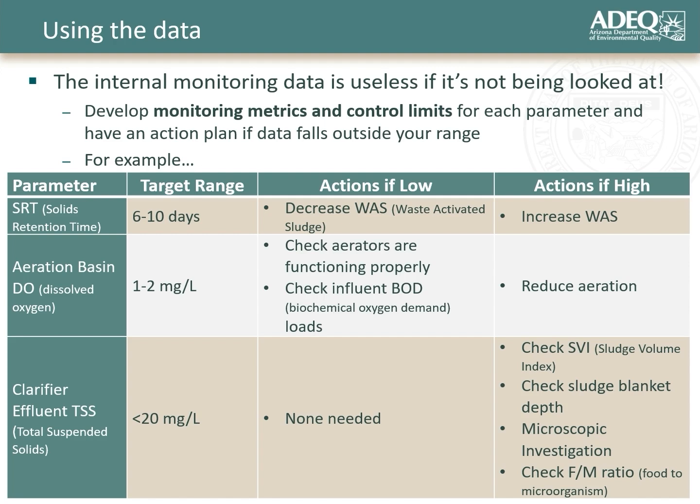Look at the organisms in your sample by looking at them under a microscope. If you happen to see a good diverse community, maybe things are looking well. But if you're starting to see less diverse and starting to see organisms that are not ideal for your activated sludge system, then maybe you look to make some modifications. And lastly, check your food to microorganism ratio. That is always a very important thing to evaluate, and then make appropriate adjustments.